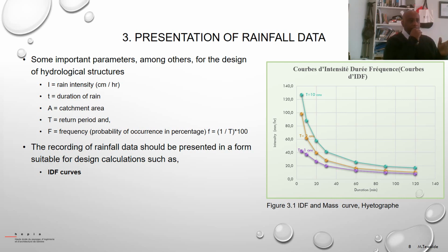For example, in a city where we are living, if engineers use one standardized intensity duration frequency curve that may be developed by the city, the municipality, or any organization or institution that does hydrology, once they standardize it, then engineers can use it, so it will help the consistency of the design procedure.